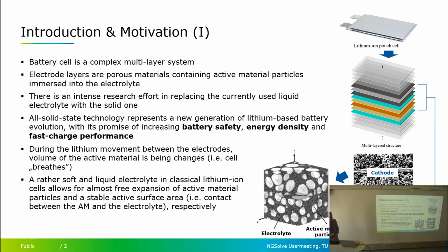The cells with liquid electrolyte have some pretty distinct limitations. One of them is a safety limitation. You've probably seen electric vehicles on fire. This is due to a violent thermal reaction called thermal runaway, and the most common culprit for that is a liquid-based electrolyte. Other limitations are in energy density, meaning vehicle range, and power density, meaning fast charging performance.